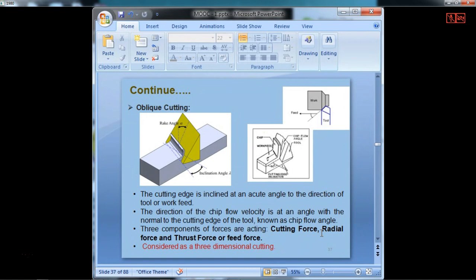If you had a cutting process where the radial force and the feed force on your instrument read absolutely zero like a flat line, and you only see the cutting force at a high level, then that would be the orthogonal process. But generally in practice you won't see that, because you have the tool angles and inclinations and all these things. Thus all the processes are oblique cutting processes.